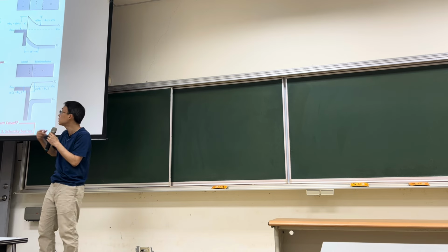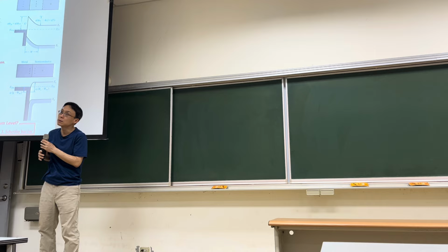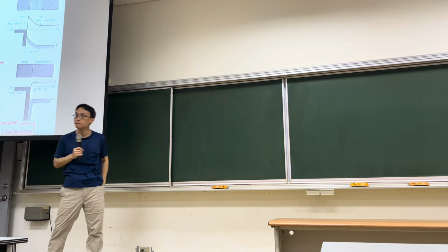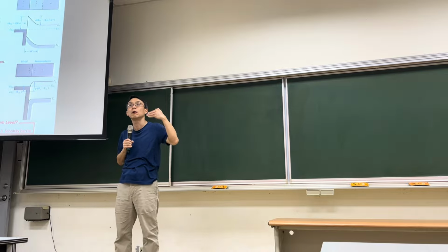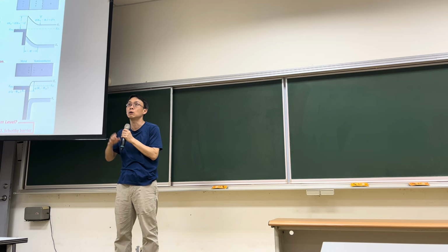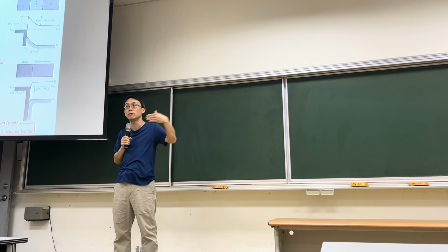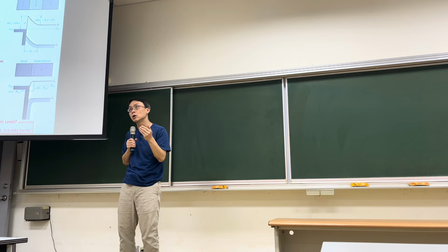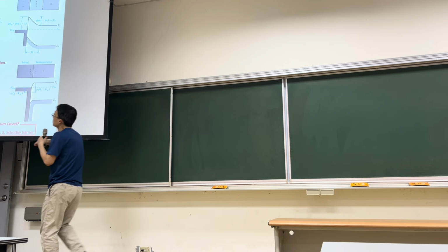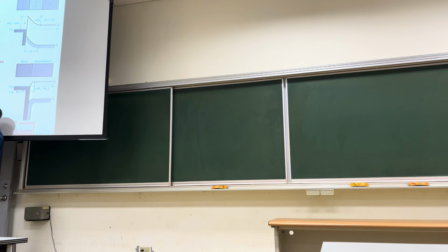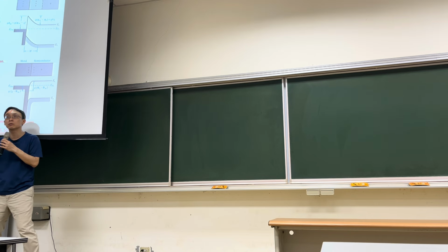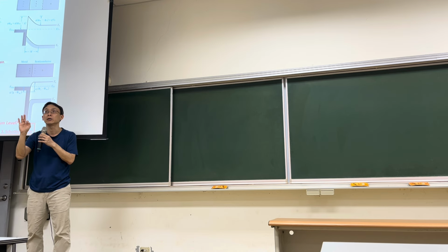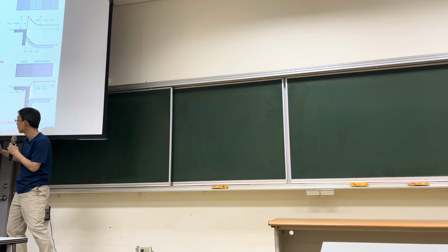For the Schottky contact, which is on the left side, you can see there is a Schottky barrier because the band is bending up. So this will impede or block the currents flowing from the metal to the semiconductor, right? So you need to choose the metal with the smaller work function, right? So I told you, you have three key parameters to memorize. Make sure you understand the three key parameters. The first one is work function, right?